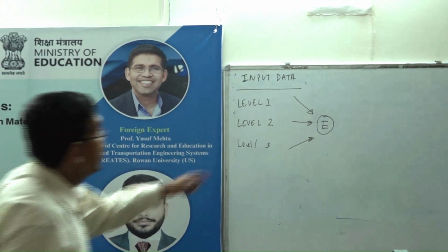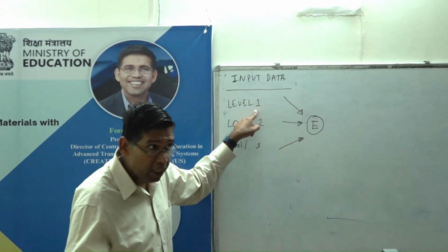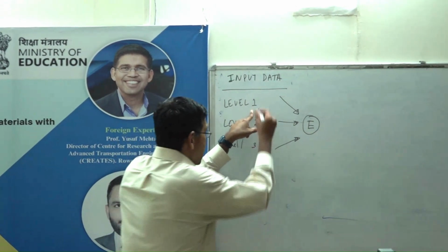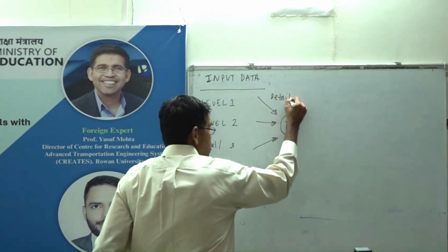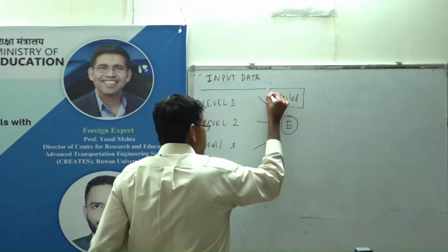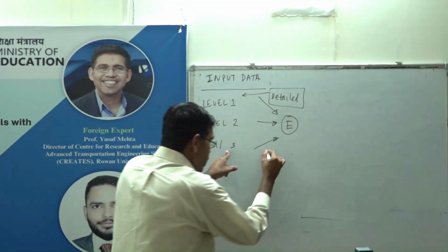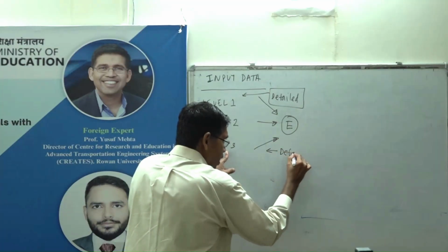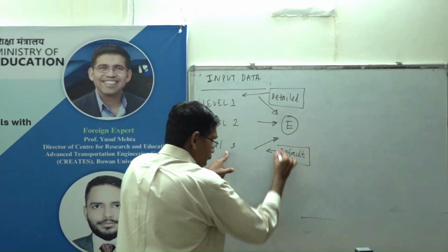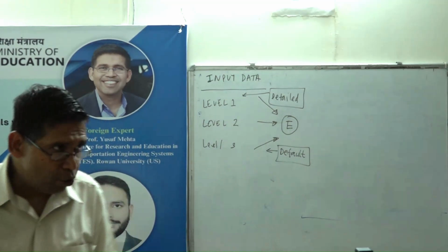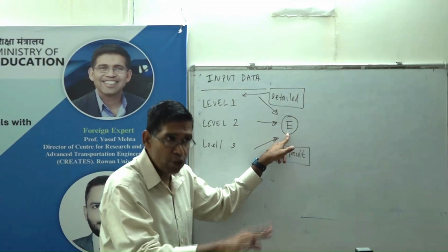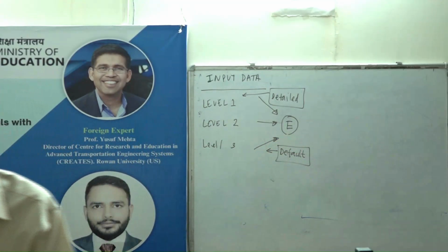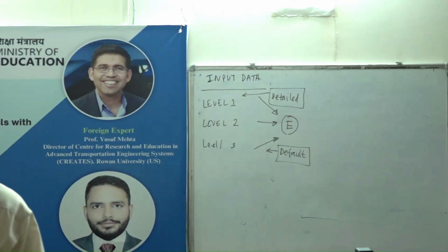So if I am willing to measure resilient modulus in the lab, then it is level 1. This is the most expensive, most detailed. So that is project specific. Level 3 is default values. If I give you soil characterization and I estimate the E value, then that is that. So all 3 will lead to E value. E value is what goes into the pavement design, like the AASHTO 93. Everybody with me so far? Like the AASHTO 93, E value is the most important one.